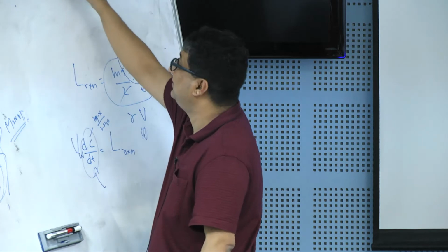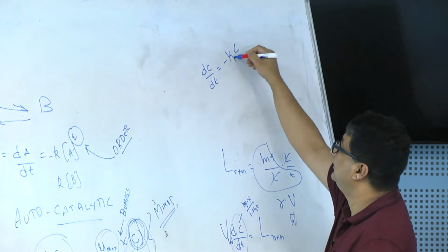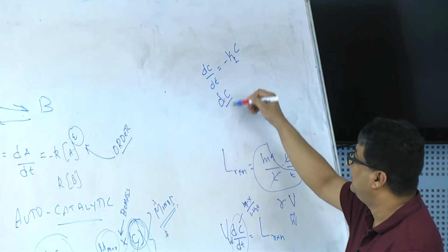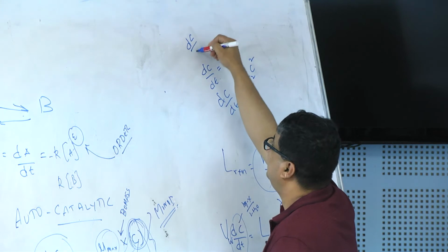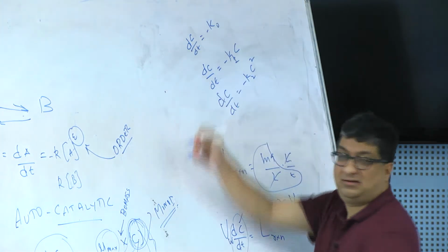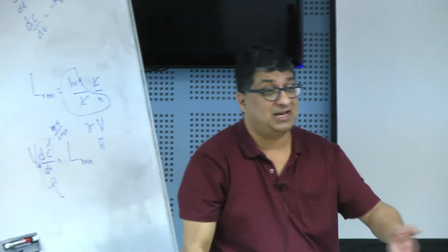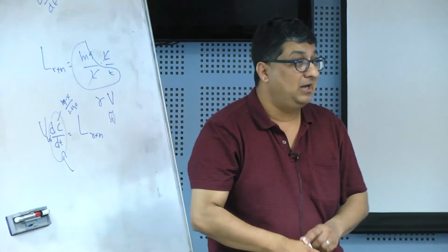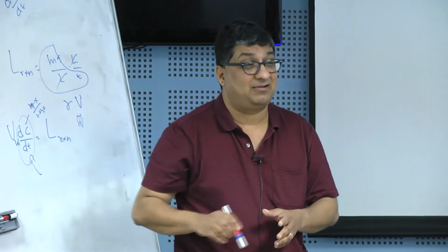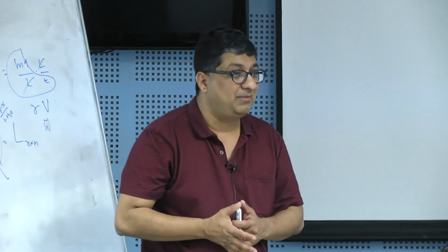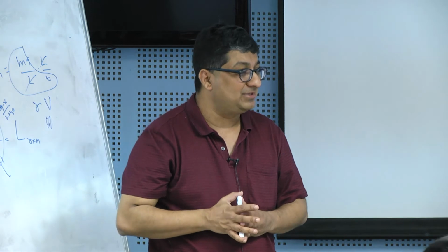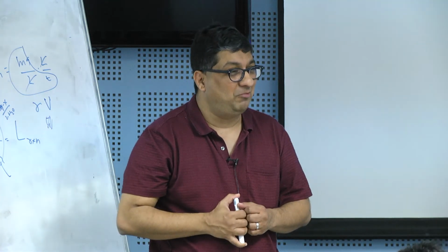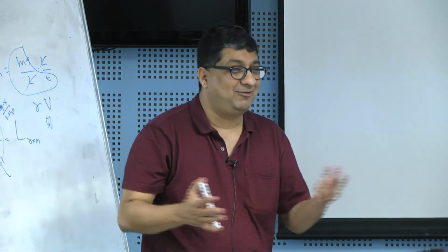If I have a first order reaction, that's my first order reaction. Then I have C squared, and so on. These are the three most common reactions that we try to fit, not because most of these reactions are truly first order, truly second order, or truly zero order, but because having nice round numbers there makes our mathematics a little bit easier. If I put 0.97 instead of a first order, I have a highly nonlinear equation. If instead I say, well, there are measurement errors, I'm going to make it 1, no big deal, and now I have a nice little linear equation that I can solve.